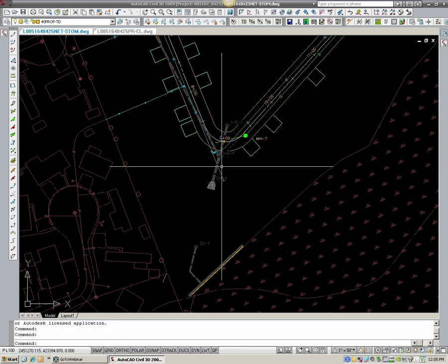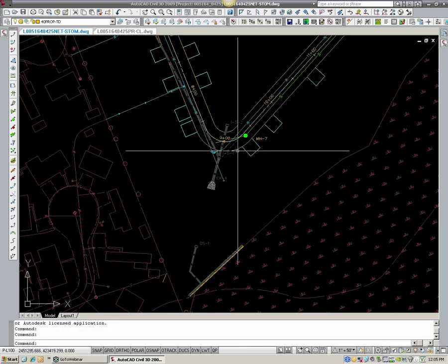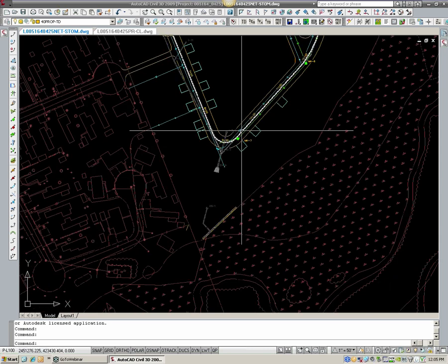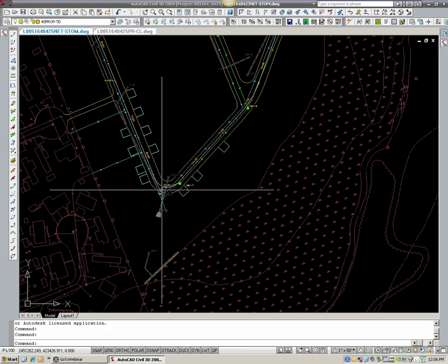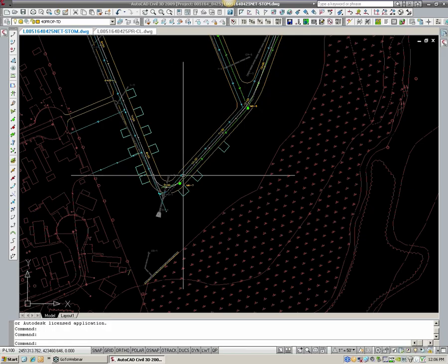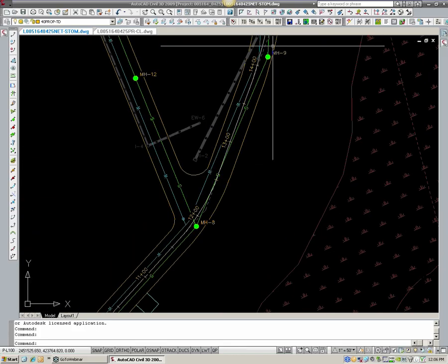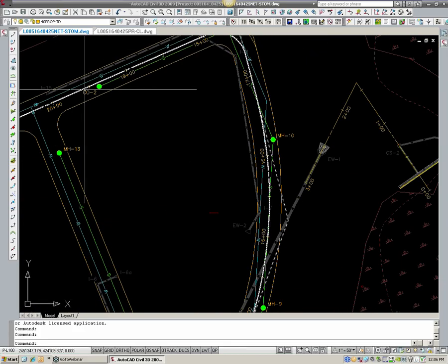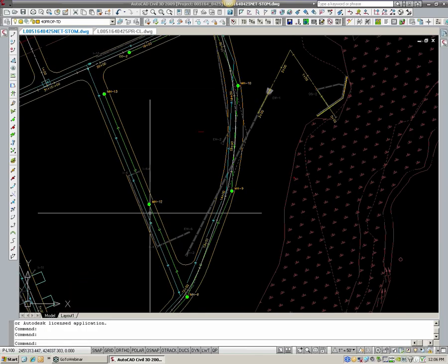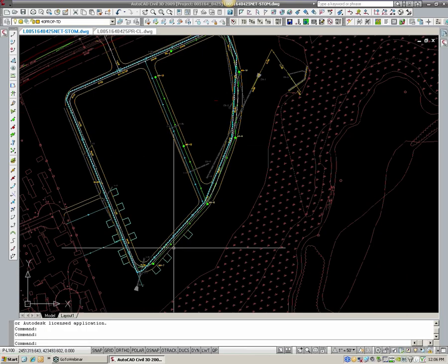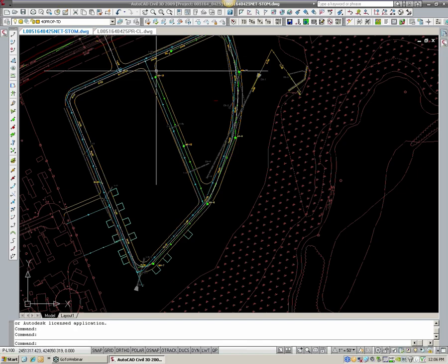In Civil 3D Pipe Networks, an entire site usually resides within one network, where Land Desktop worked more on the run concept, where one consecutive string, for example, this sewer line, would be a pipe run coming up through here all the way to its very end. And then this would be another pipe run in Land Desktop. In Civil 3D, this is one sewer pipe network, okay? So all these pipes reside in the same network.